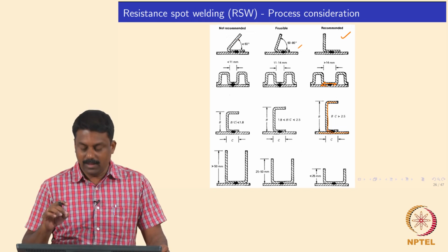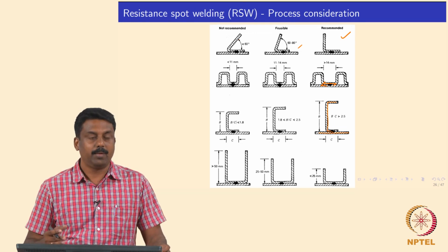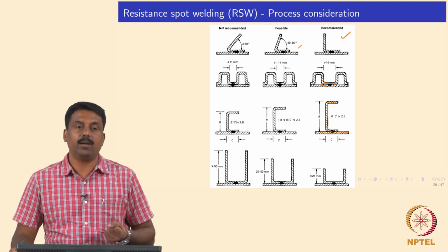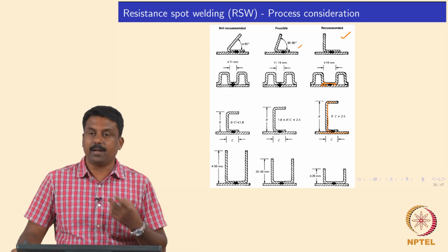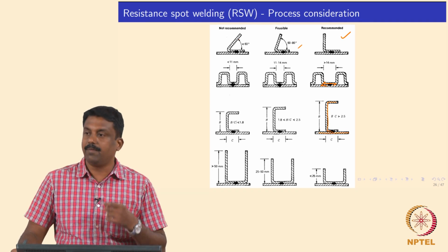So you cannot just choose a point and weld, because the load distribution is a function of the geometry of your component. They do structural analysis for a component and identify the location where it is ideal for the spot weld to be.